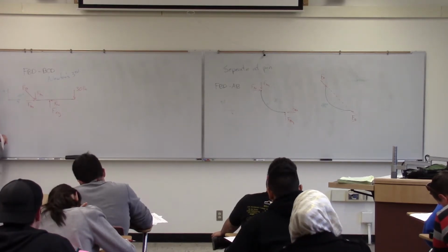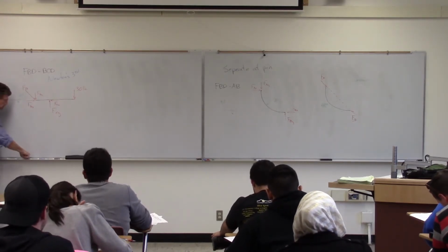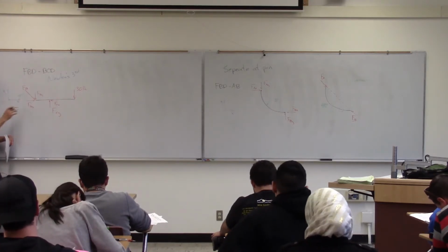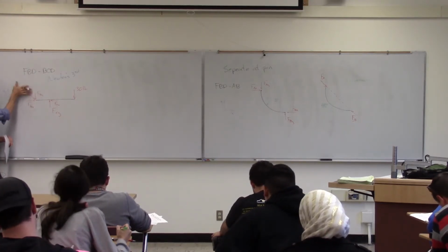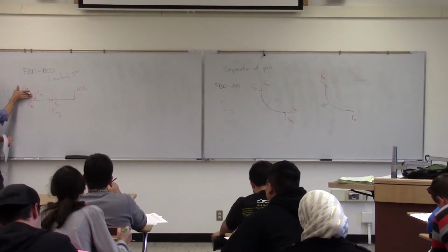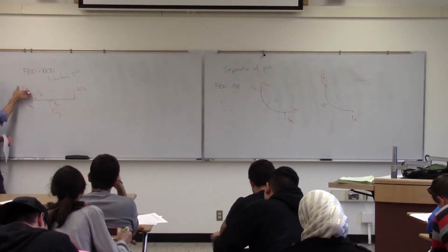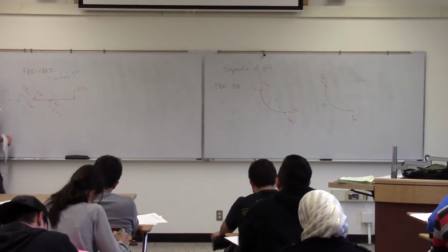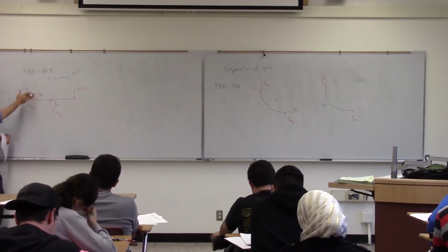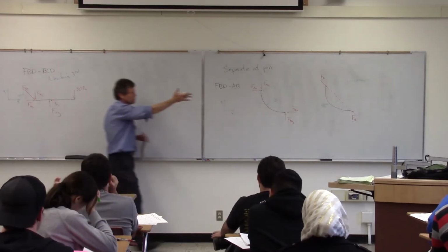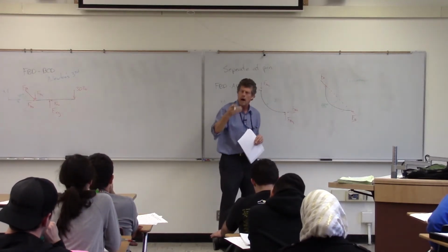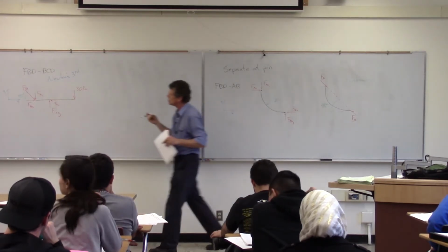But what I've done at this point is I've eliminated an unknown. When we first started this, without looking at the direction there, we had the same four unknowns that we were dealing with in the entire structure, except that we had it broken at B. But now, if I go back to this portion of the structure, realizing that I've got a two-force member, I've established its direction.